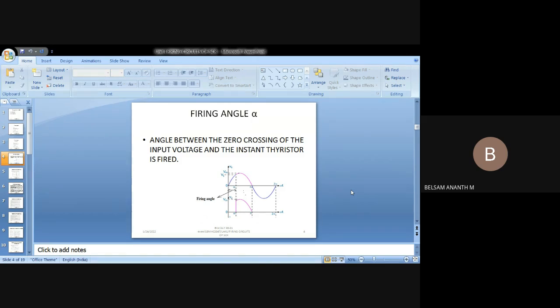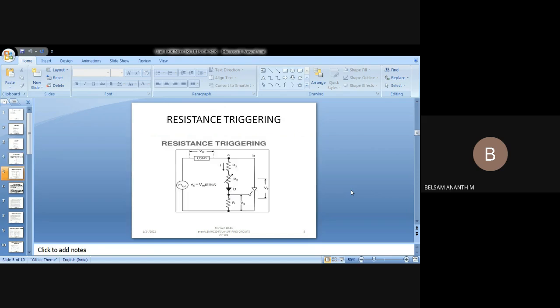Okay, fine. Now, in the first case, we are trying to give triggering at, I think, 90 degrees. For example, not exactly 90 degrees, say 45 degrees or 50 degrees in that diagram. That interval is called the firing angle, or alpha. Suppose I consider 90 degrees, it may be like the center part. Between 0 to 180, I may have a center line. From that, I will have the remaining regulated output value.